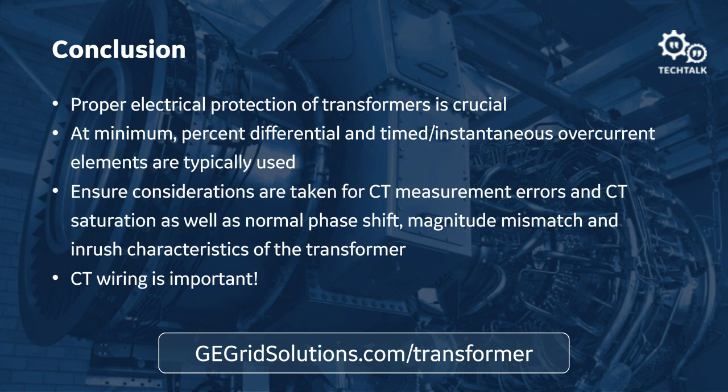Someone asked, what is the suggested GE transformer protection relay for 67 MVA, 2 winding, 3 phase, 230 kV to 13.8 kV? You could either use the 845 or the T60. It depends exactly which functions you're looking for, but being that it's on a higher voltage transformer, we'd probably recommend the T60. But if you have a specification or anything, more information on that, let us know. We can give you an order code and more information.